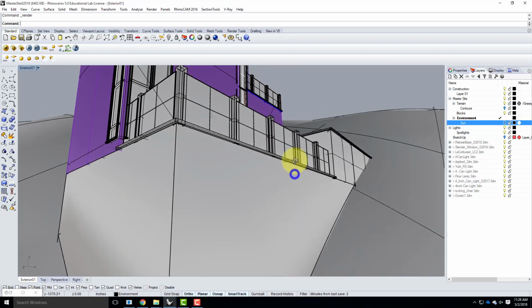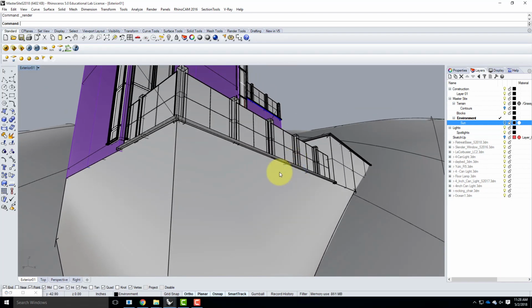And part of the reason that I'm doing this style of light is because it's a little bit different than the other lights that I've done. I'm going to create a rectangular light this time rather than a point light or a spotlight. And the thing about rectangular lights, and the reason that I don't emphasize them much early on, is because the settings are very, very arbitrary based on the size of the rectangle. So it's not as prescriptive as with a point light, where I set the wattage to 40 watts and it looks approximately like a 40-watt light bulb. The rectangular light doesn't work that way.